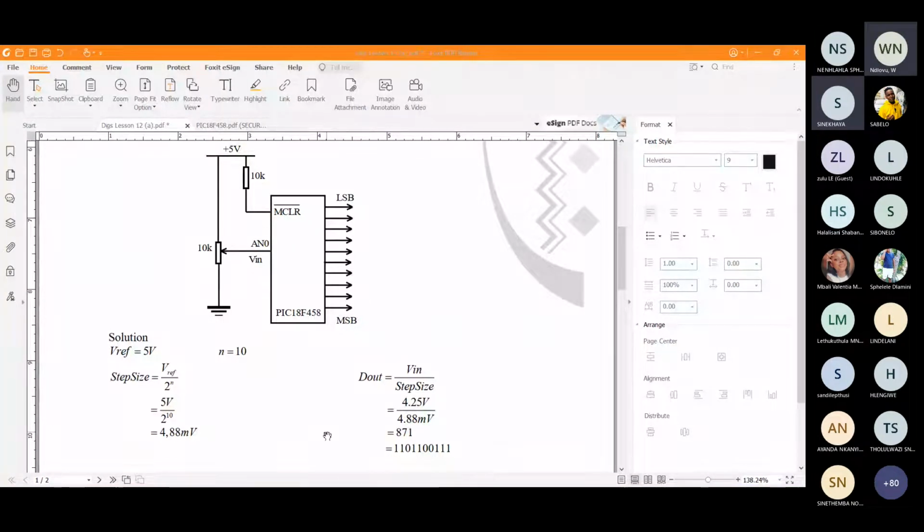Okay. Now, here we have a potentiometer. This potentiometer, we are changing the resistance between ground and 5 volts. As you swing this here, you are supplying a voltage here. So this V-in is the voltage that we have between the ground and the supply or this wiper. As you see that I had two dots, as I was clicking that dot, I was changing the voltage that I'm applying here. So V-in is the voltage at any point in time here.